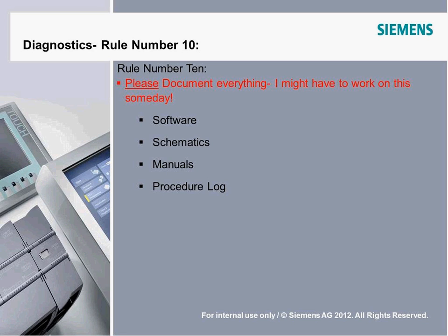And diagnostics-wise, we can actually turn on things like wire break detection and so forth, so we actually do know if there's a wire break or if it actually can't achieve its 4 or 20 milliamp signal levels. It'll tell us that as well. 0 to 10 is kind of open-ended. It just, 0 to 10 appears at the PLC and away it goes.